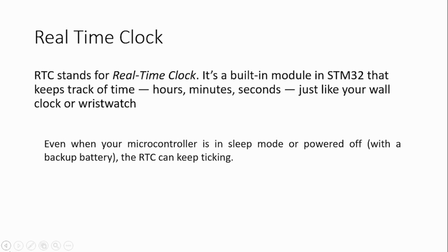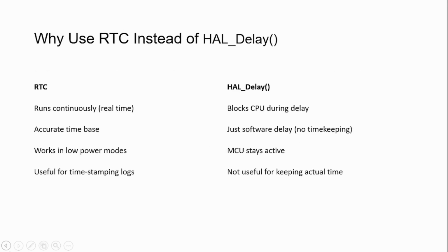Now, as an initial demo, I will simply compare this RTC with HAL delay. We are going to turn on the LED with an interval of 1 second, and we will generate that 1 second interval using RTC. Along with this, I will also display the time on UART. Time means hour, minute, and second, right? Like a digital clock, HH, MM, and SS. So I will also use UART to display this information.